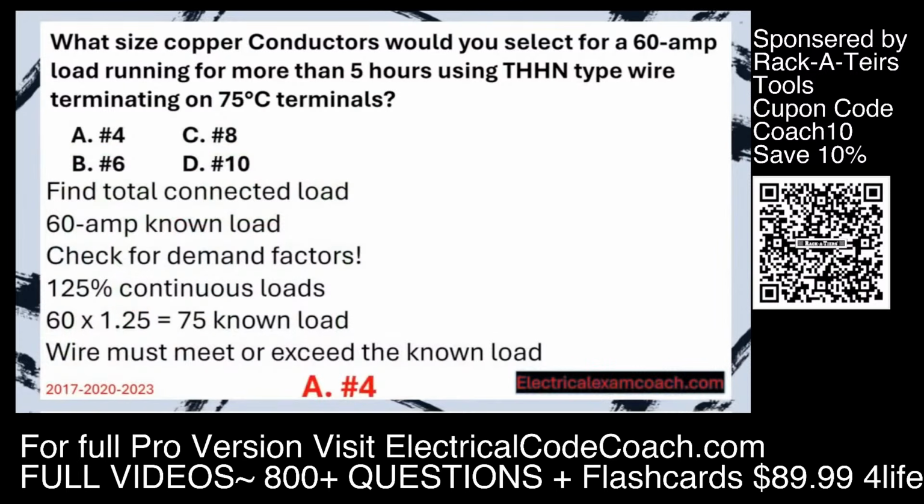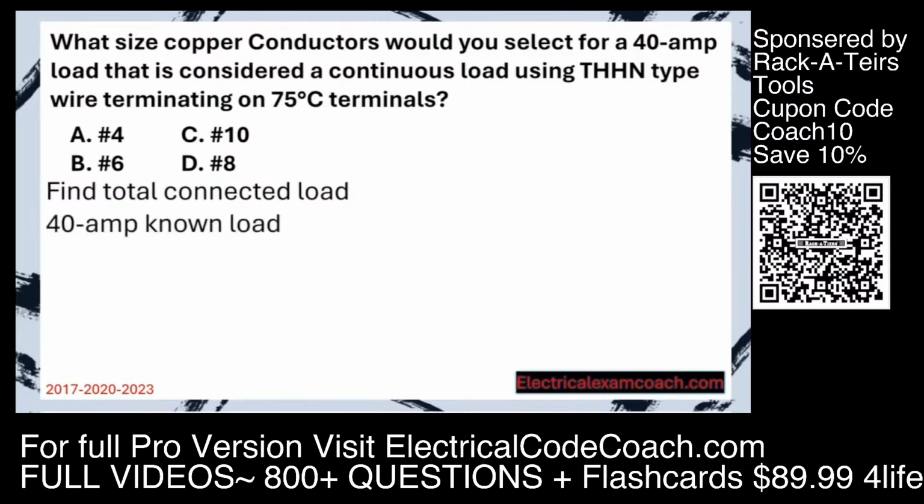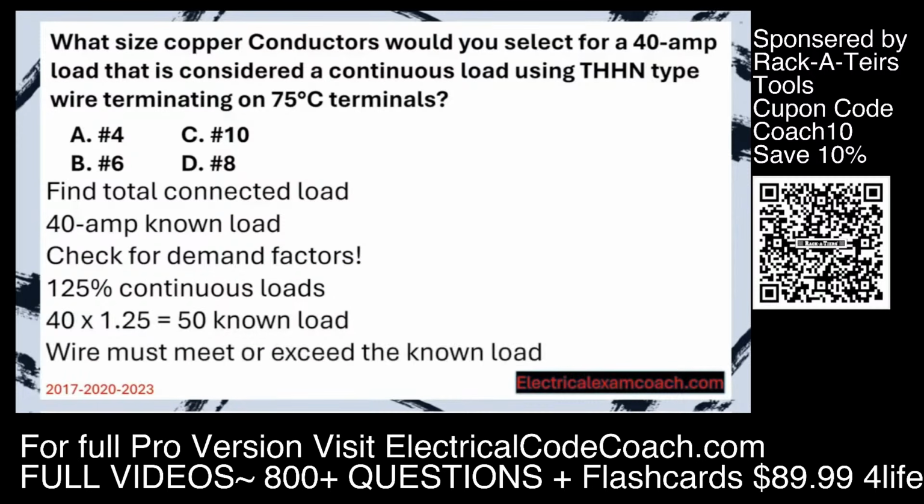Let's get to it. What size copper conductors would you select for a 40 amp load that's considered a continuous load, using THHN type wire terminating on 75° C terminals? Step 1, find the total connected load. In this case, our starting known load is 40 amps. Well, we have to check for demand factors, but they've already let us know that it's going to be considered a continuous load. We take our original known load, multiply it by 1.25, and that gives us a new known load of 50 amps. And all of our wire must meet or exceed the known load.